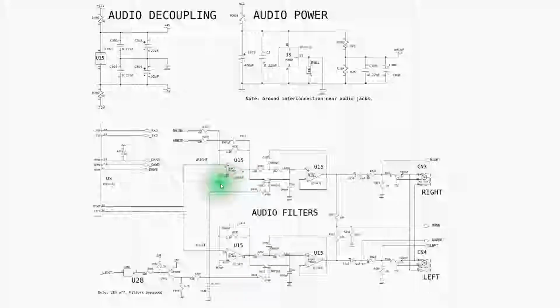Notice here that the positive side of both of these op amps goes to this voltage reference. That's this 2.5 volt reference. So my assumption here is that these audio outputs swing from 0 to 5 volts. The Poly chip's powered from 5 volts, and they swing someplace in between, that 0 to 5 volts. And by having this 2.5 volt reference here on the positive input, I can get the output of the op amp to swing between plus and minus 12.